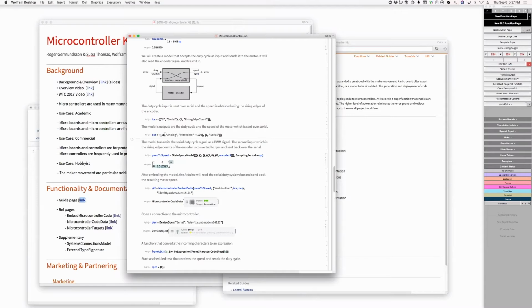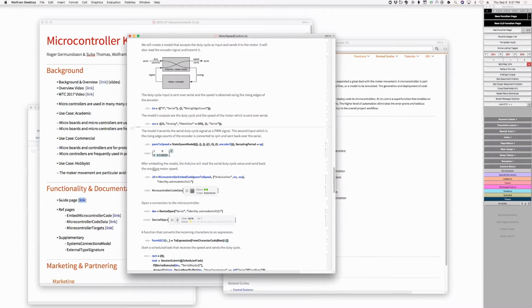So these things are going through an A to D into something that is, even though it says analog, it's really 256. Yeah. These microcontrollers had built-in A to D and D to A converters, right? But they're not super high resolution, as you heard. Yeah, I understand. They're 256, right? 8-bit, right? Okay.